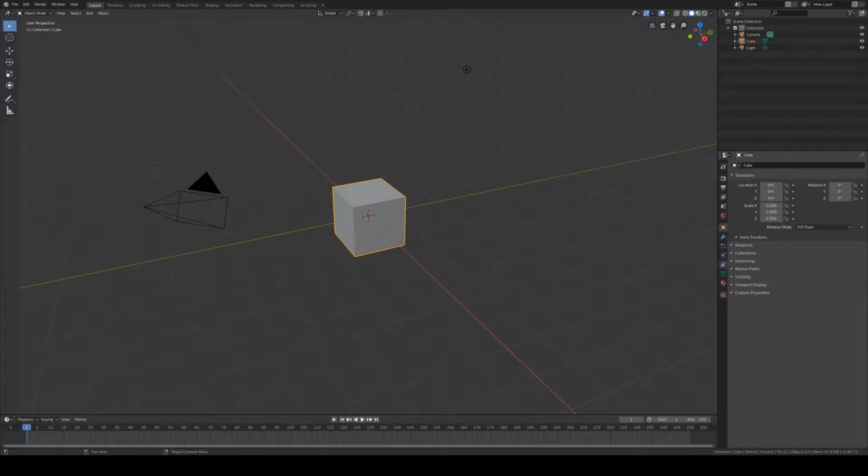The first thing I'm going to do in this scene is add what we call an HDRI, which is a specific type of image that can be used as essentially a sky dome. The nice thing about this is that it reflects light in your scene, so it acts as a light source, but it does it based on the color of that image that wraps around the scene.